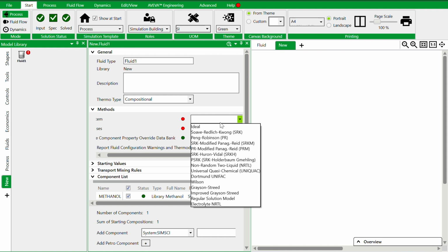In most of the chemical industries, we can have NRTL or Peng Robinson as a common thermodynamic package, and for the hydrocarbon industries or petrochemicals, you can go with Peng Robinson or SRK. I have already discussed the method selection in our earlier session of the series.